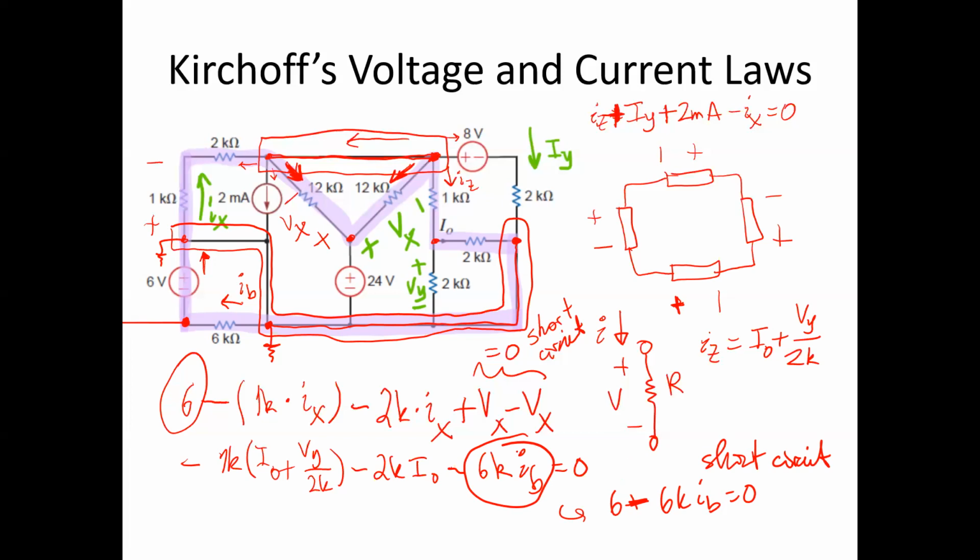Okay, so this problem was really an exercise in recognizing short circuits and being able to take advantage of the ease that provides. A lot of people in class went through the trouble of trying to write the equation for this very large supernode on the bottom, but it was quite unnecessary. You could have simply said plus 0 and then nixed out those two terms in the equation and you would have been done.